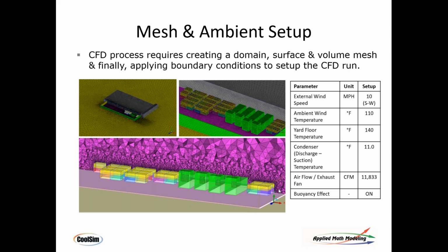Yep. So experience helps a lot, but what you're looking for there is numerical differences based on density. Once the numerical difference of the solution begins to flatten out and not change much, you feel you've achieved a level of mesh density high enough to capture the physics, correct? Yes. That is a scientific way of doing it. But experience also counts, yes.